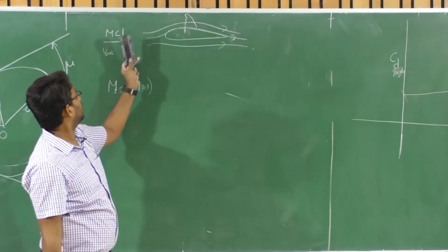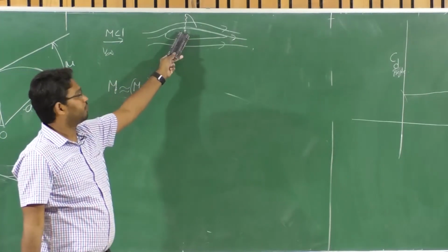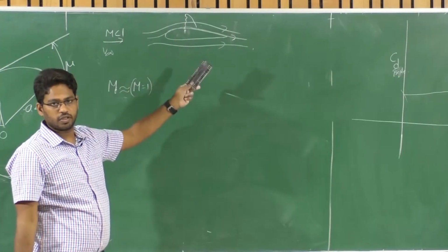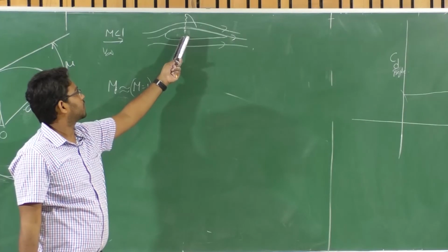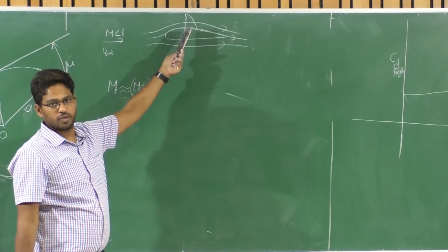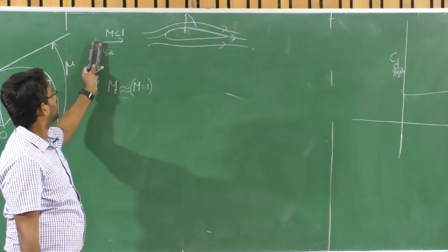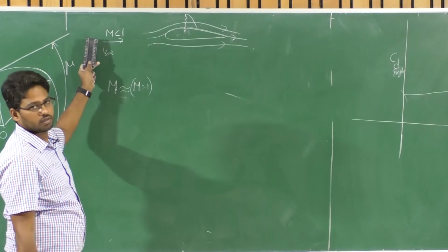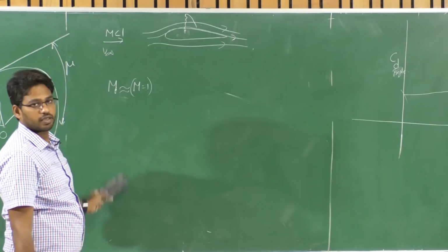You are still at subsonic speeds, but your wings see a shock wave on them, as the local velocity reaches Mach 1. That particular Mach number at which you're flying is considered the critical Mach number.